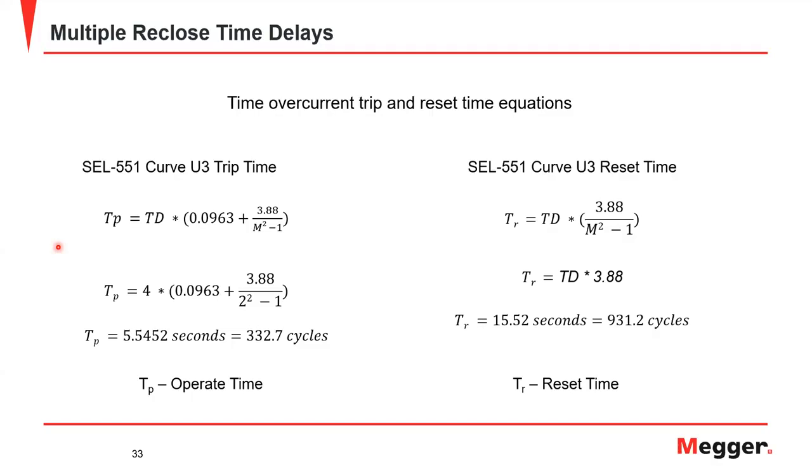Hi, another interesting question, and the answer to this one is do a proper short circuit study, and the tool that you're using can tell you what the proper coordination times are that you have to use for both. Fortunately, today, microprocessor relays can be coordinated, whether downstream or upstream, with other microprocessor relays and with electromechanical relays.